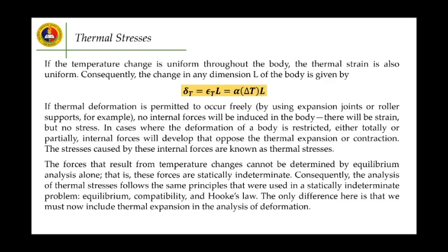elongation due to thermal is equal to your strain times our L. Basically, this formula here was already introduced prior. And just substituting our formula for our strain, this one here, which is equal to this formula. So therefore, elongation in terms of temperature change is equal to alpha times change in temperature times L.